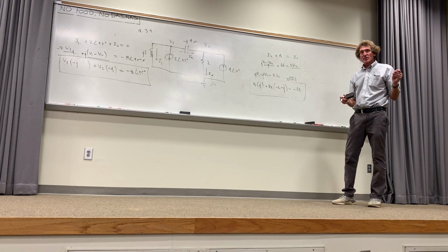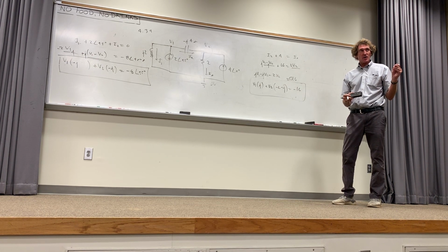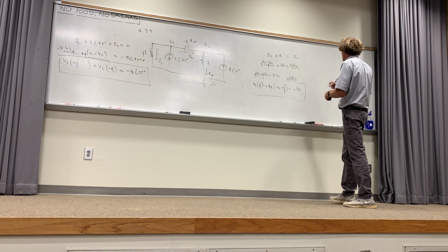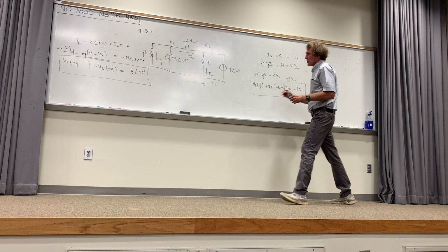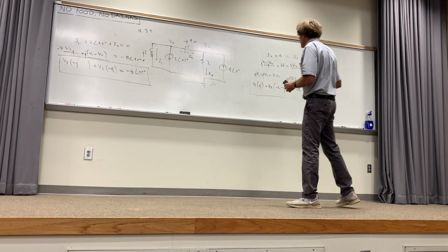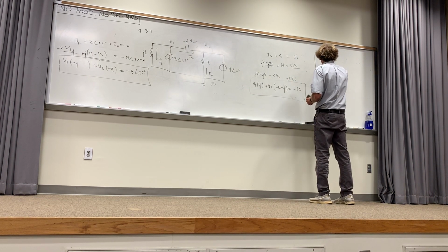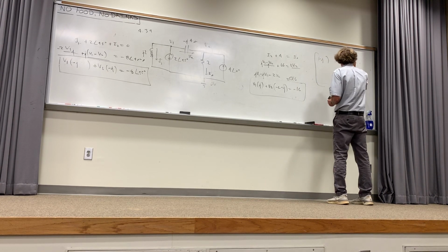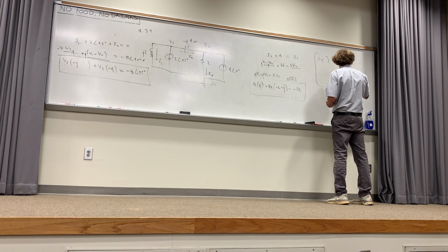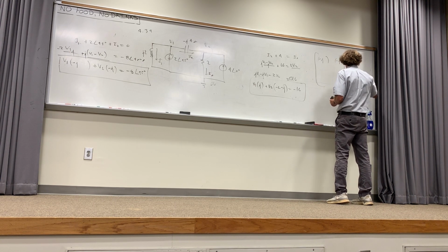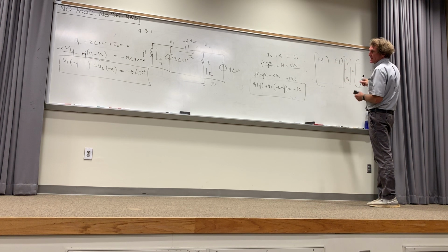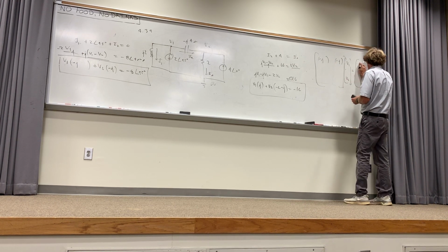Now, you have to do this on your calculators. This is a complex matrix you're going to have to solve. So here, I take the first equation, and I do this. I take the coefficients there. I've got minus j, minus j, minus j, minus j, V1, V2, equal to, then in the block form on this side, first coefficient up there is the coefficient on the other side, minus 8 at 45 degrees.